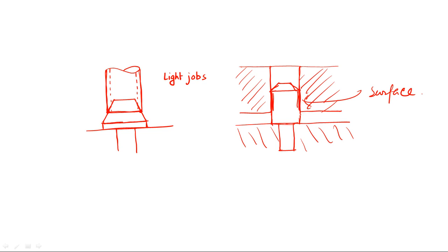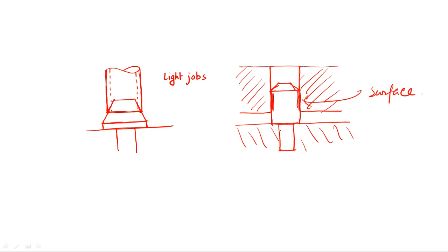Okay. Next, we can hold the cylindrical shaped jobs or hollow shaped jobs with other systems also. Suppose you have an object, and the workpiece looks like this shape. To hold this object we can use a pin, and the name of that pin is a diamond pin. Or we can use a circular shaped pin to hold this point of the job.